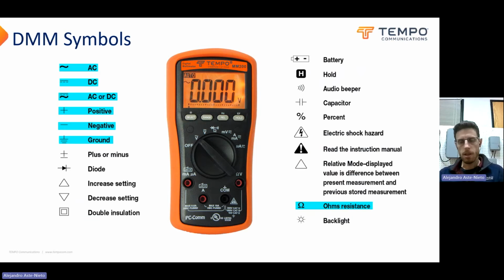On the multimeters themselves, they will put symbols to symbolize these different ideas. If you're measuring AC voltage, you won't see VAC, you'll see a wiggly line V, right? And that means AC voltage. If we see a straight line with a dashed line underneath it, that means DC. So this is DC voltage that we're measuring right there. And then certain things they can measure both, whatever you throw at it. So this one, when you take current measurements, it can do either one, AC or DC.